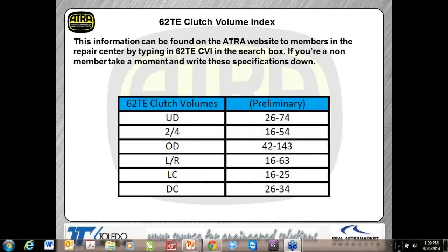So now that we don't have that ring rotating in there, it should save the problem of having those ring lands wear out. The only thing, obviously, this is a new update, a new fix, so I don't know what the new rings will be like as far as wearing the drum on the top that rides on it. It's all stationary, so it shouldn't be a problem there either. There's the part number, but the actual old part number will supersede to the new part number. But like I said, if you want to write that down or to actually take another print screenshot, you can have that there.